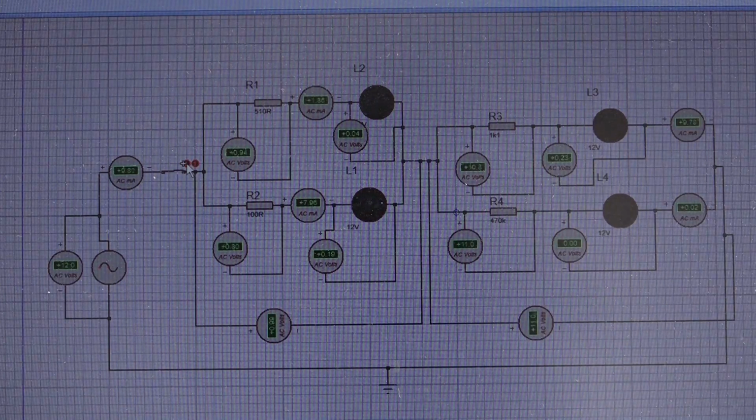Then at point N, we have to measure AC current. The calculated value is 2.343 exponent negative 5 milliampere. For that one also, you have to change the measuring device into an AC microammeter, because otherwise it reads 0. Because you know the calculated value, it can train you about the choice of the right measuring instruments.